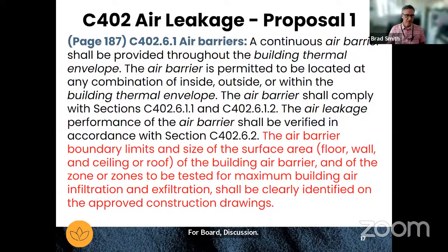And for those that don't know, the city of Fort Collins has been performing commercial building air tightness testing for approximately 12 years now. Our metric is 0.25 CFM 75 per square foot of envelope area. It is pretty common, if this does not exist on the construction documents, that we see different numbers from the architect, even the builder, to the test firm.